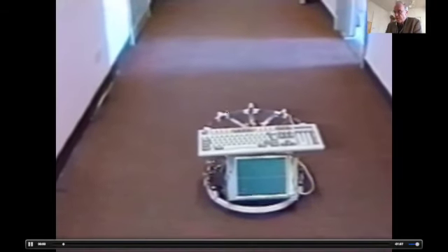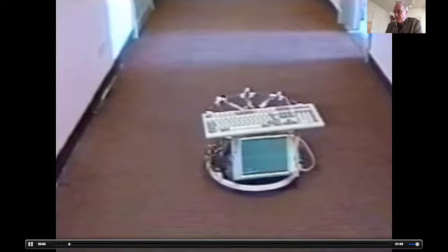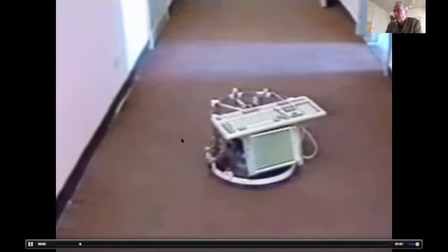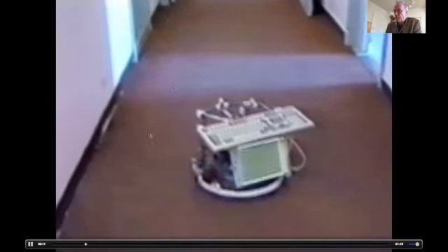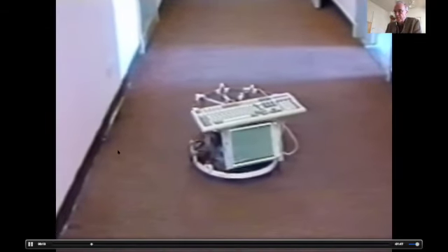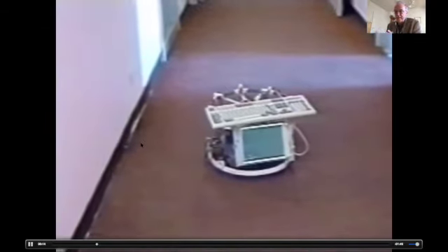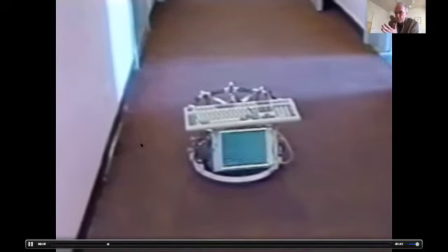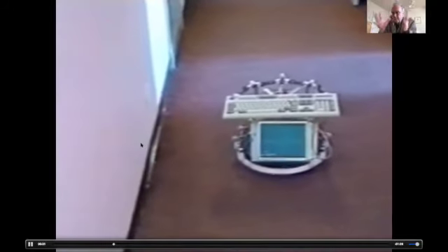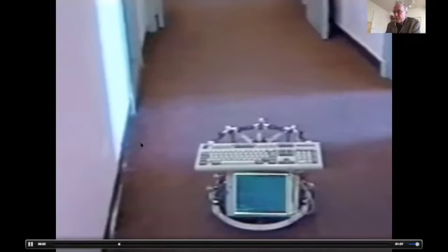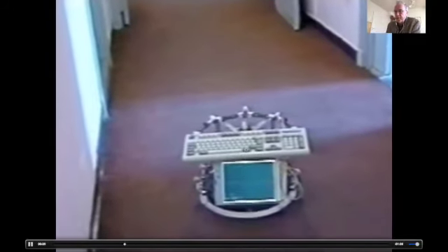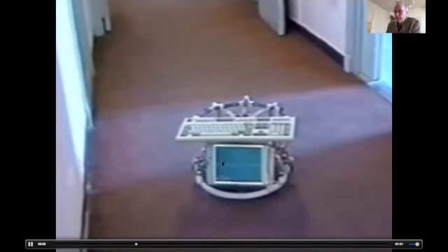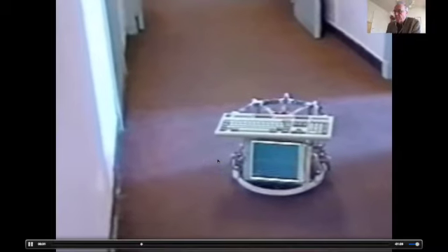In here, we do the transformation, taking these microphone readings, which are on the robot, and putting them into this heading frame. The heading frame is approximately aligned with the world. As the robot moves, this line might actually drift. Because it doesn't estimate its own orientation perfectly well, it might slowly get confused. But as long as this sound resets the peak in this frame, that's fine. If we were to turn off the sound for a long time, that would be a problem.